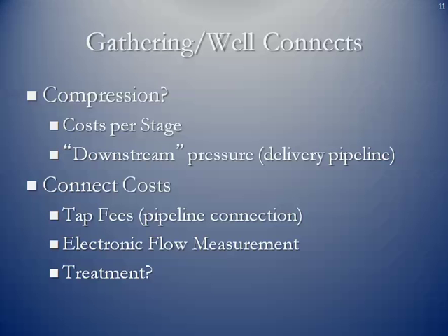And then most pipeline companies these days require what's known as electronic flow measurement. They want to be able to see from a remote location how much gas is actually flowing in. And then again, at the point where you connect to a downstream pipeline, there may be additional treatment needed at that spot, and either you pay for that up front, or the pipeline or midstream company may do that.